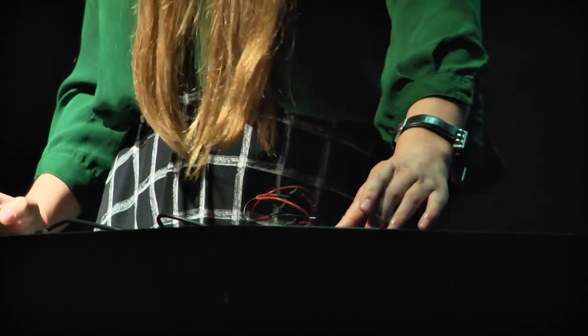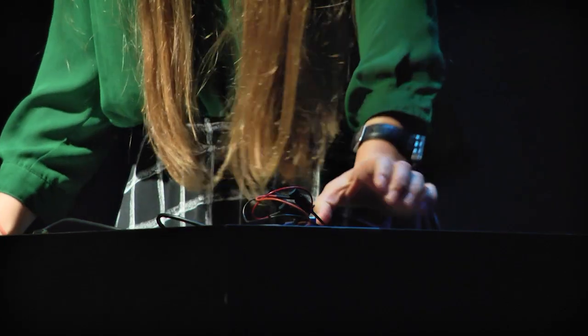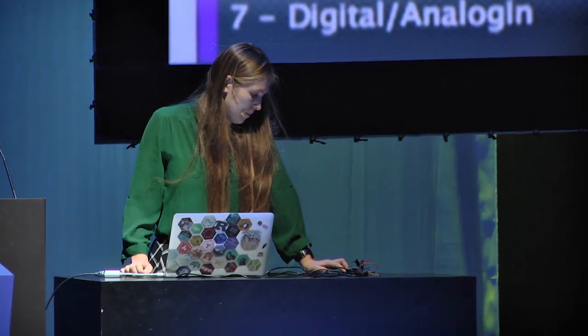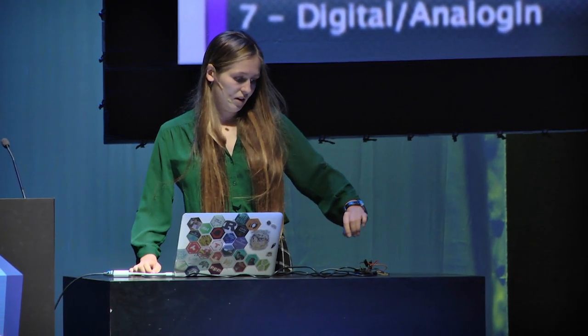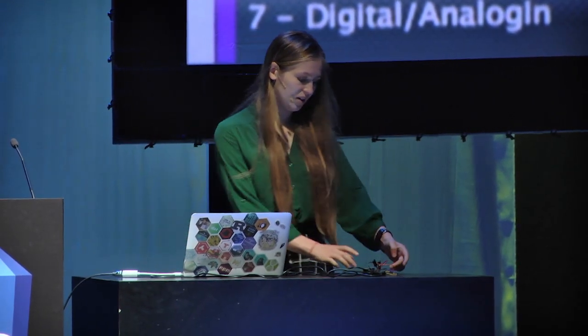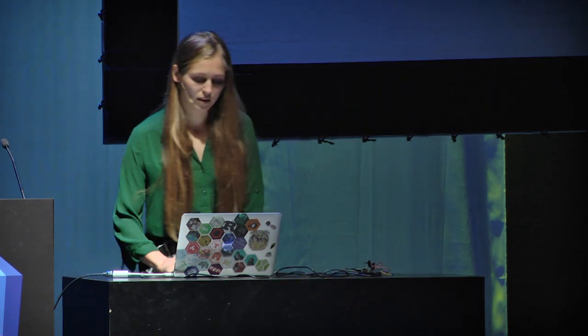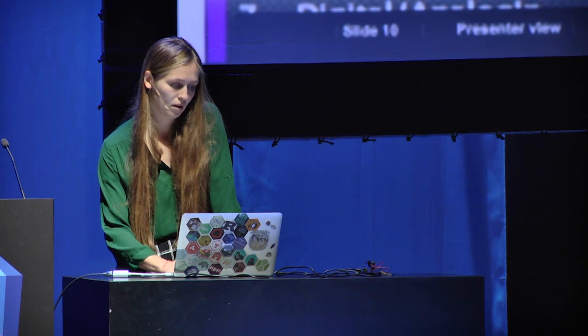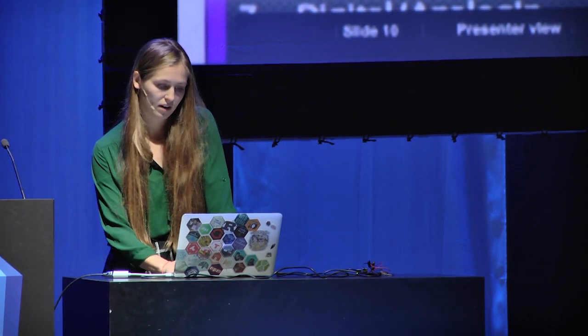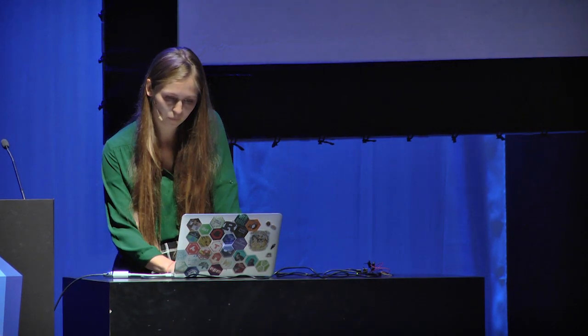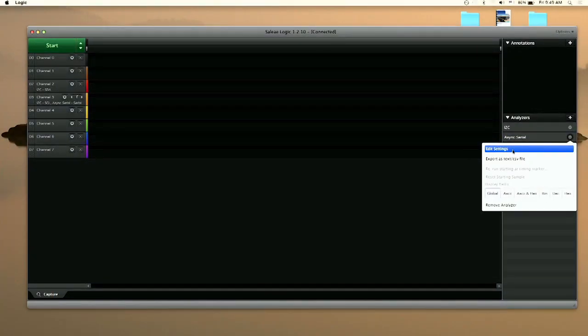So what we're doing is taking a message and sending it from the Tessel and communicating it outward. In this case, I don't even have a microchip attached to it, so it's not communicating with anything except for this logic analyzer here. The important bit is that this is the JavaScript code I'm going to send, and this stuff over here is settings in the logic analyzer, which tell it how to interpret it.